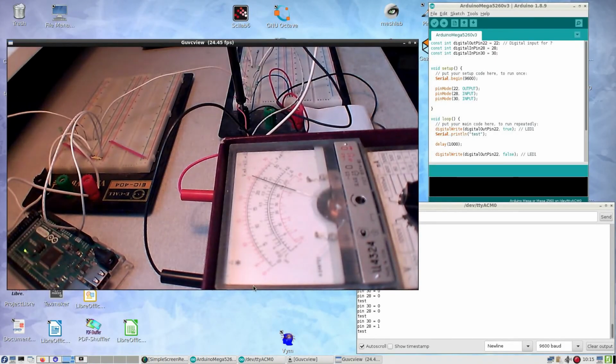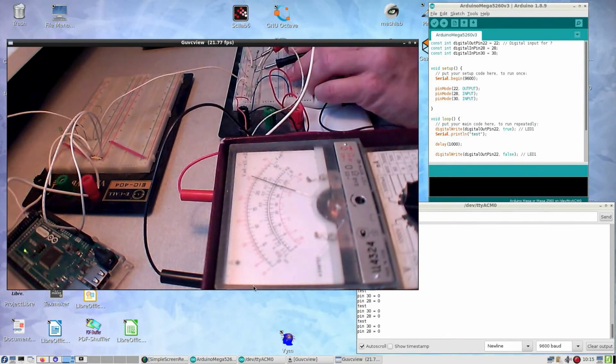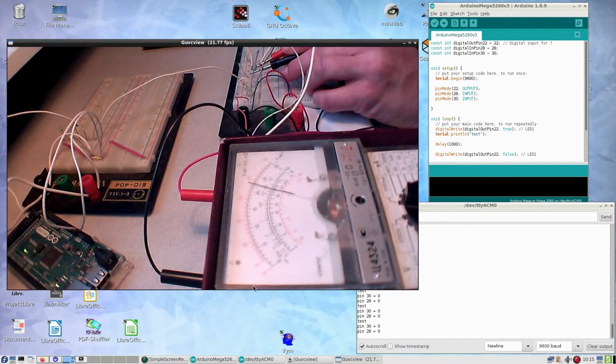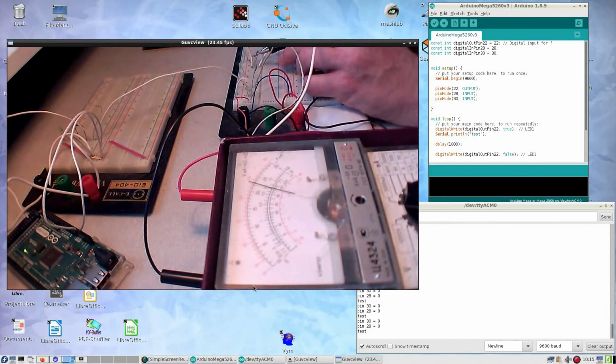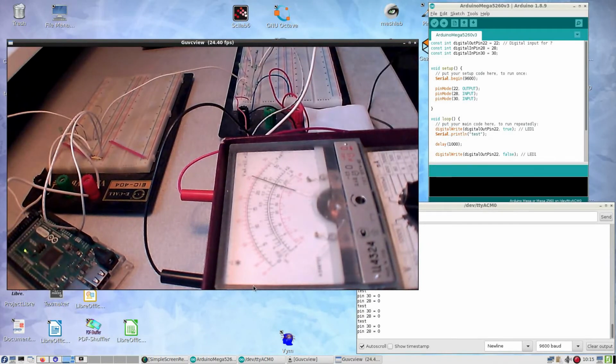And another thing you can try before messing with the resistors, measuring them. So I've put the setting of the multimeter to resistance, and now I'm going to measure this resistor, which gives 70 ohms, and then this resistor, measuring the same. So they're the same value, which means there's something else going on.